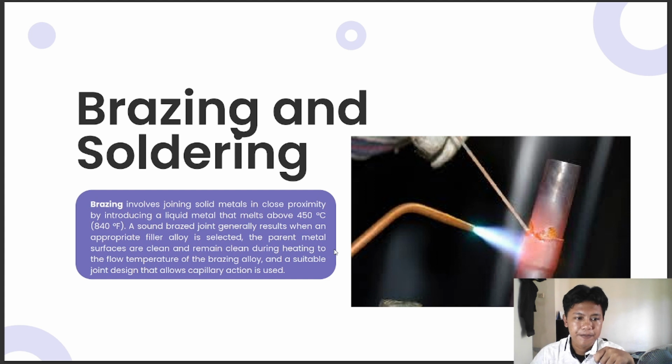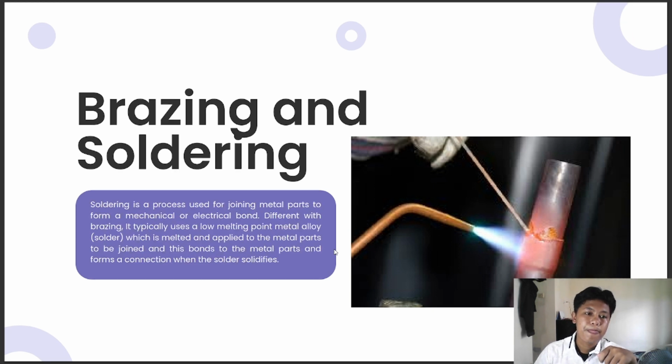Brazing and soldering. Brazing involves joining solid metals in close proximity by introducing a liquid metal that melts above 450 degrees Celsius. A sound braze joint generally results when an appropriate filler alloy is selected, the parent metal surfaces are cleaned and remain clean during heating to the flow temperature of the brazing alloy, and a suitable joint design that allows capillary action is used.